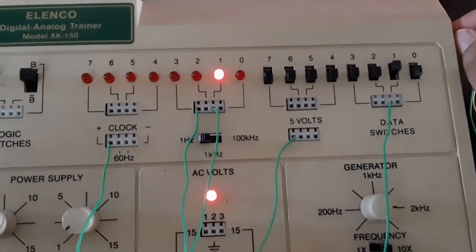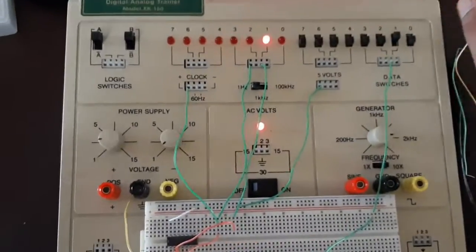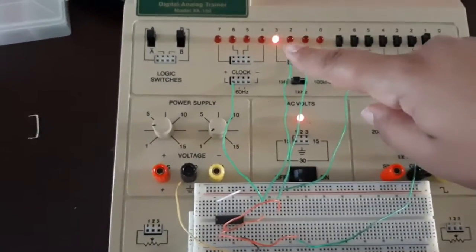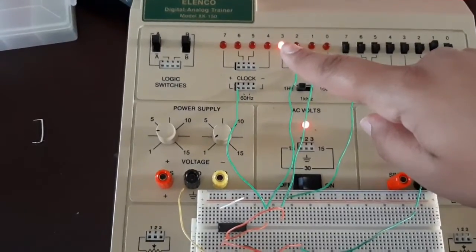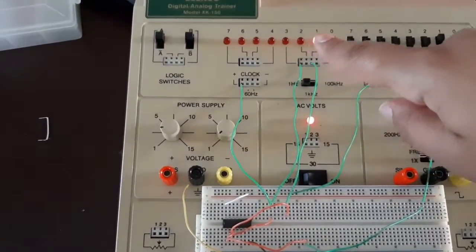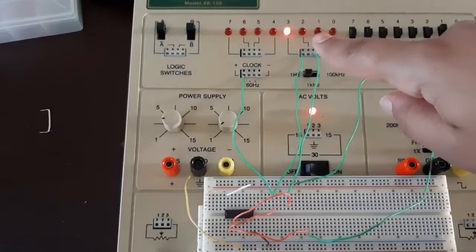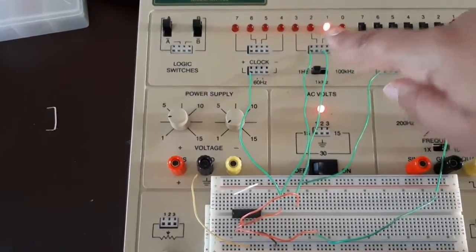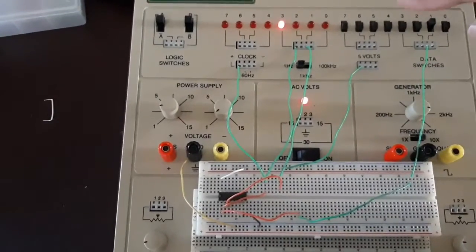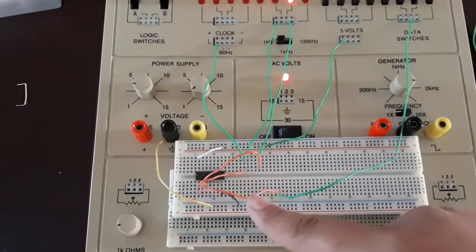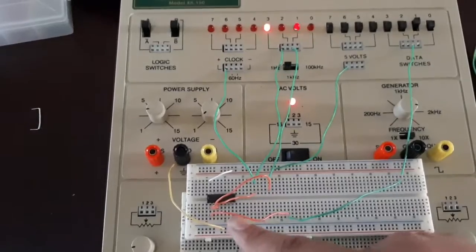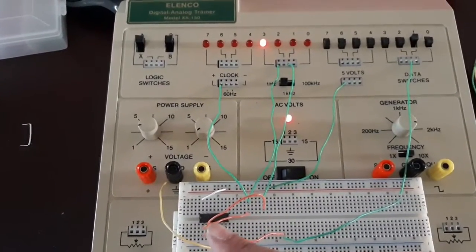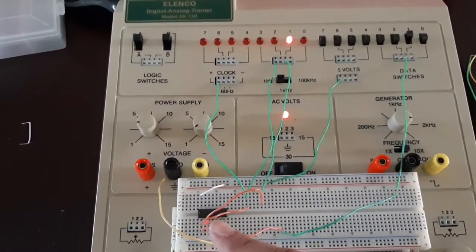Okay, cool. Anytime the square wave is high, the output is low. And anytime the square wave is low, the output is high. That is because we have one input consistently high, and with the exclusive OR gate, only one input can be high for the output to be high.